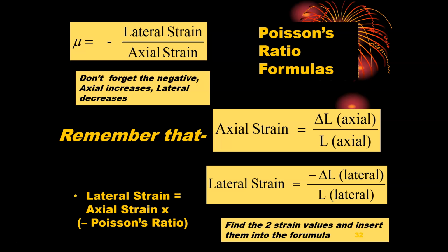Or we can round it to negative 0.005, or negative 5 thousandths. So the lateral deformation in z is the lateral strain times the original length. So the lateral deformation equals negative 0.007 again, times the 500 thousandths, and the lateral deformation is negative 0.0035.